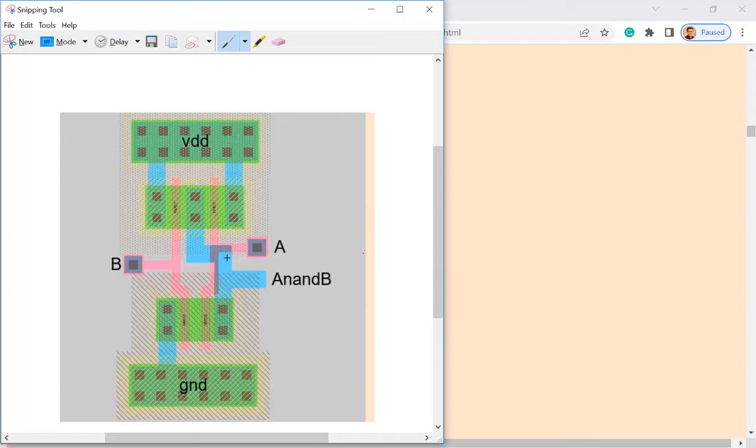So what I did, I guess, is I introduced a very short metal 1 trace to here, and I built a metal 1 to metal 2 via, right? And then I put a metal 2 to here, and then metal 2 to metal 1 for this one. No, you don't have to go down one step, right? So these are A and B, but both in metal 2. Like that. That's what we did, I guess, in the lab. All right.